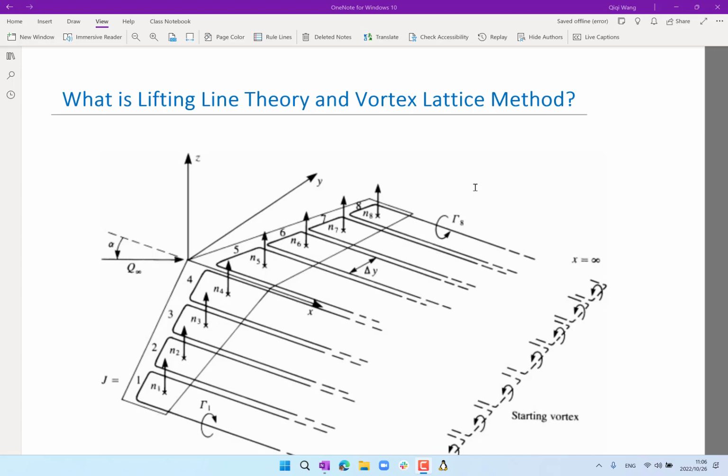And from that circulation, which was a single vortex coming from one wingtip to the other wingtip, we figured out the circulation of the wingtip vortices that come out of the wingtips. And using the strength of these circulations, we figured out how much downwash is on various locations of the wing.